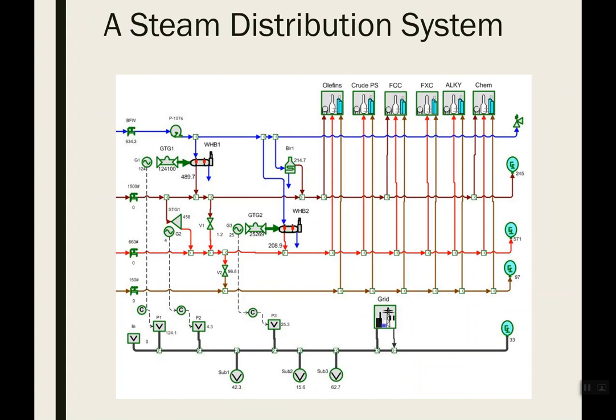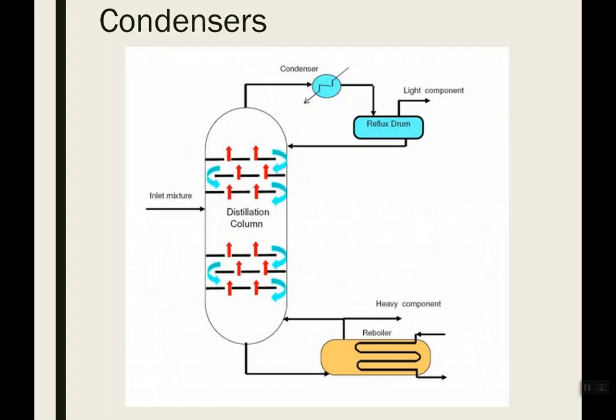Okay, so this is an example of a steam distribution system. This is a very, very simplified example. You might actually have several different levels of pressure in your steam line. You might have superheated steam at high temperature and high pressure, up to 1500 psi. You could go down in various phases. We typically had problems with our 150 psi line because that was the coolest and the closest to condensing.